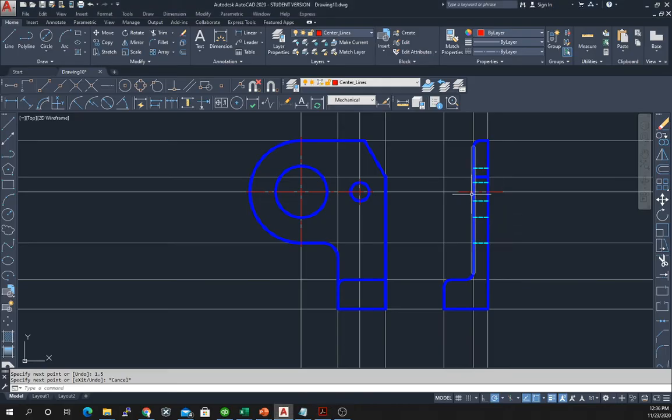So I started here, and then I did a track. I didn't hit my mouse button. I did a track so that the line would start out here. So it would start 0.5 inches out. So I made my length of this line 1.5 inches, which means I start 0.5 inches out. I'm 0.5 inches through this part, and then I'm another 0.5 inches on the other side. So I know I have a symmetrical line throughout this part.